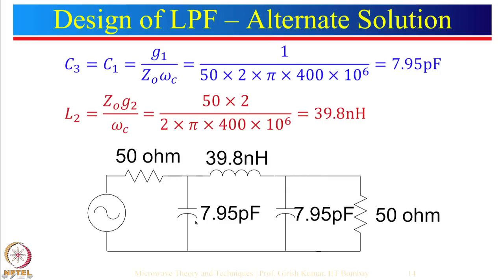You will know what the response is, and then check those things, and depending upon whether it meets your requirement or not, you can keep on doing the modification. Sometimes you can add inductors in series or in parallel to realize the desired value of inductor. Same thing you can do for the capacitor. You can use 2 capacitors in series or parallel to realize the desired capacitance value.